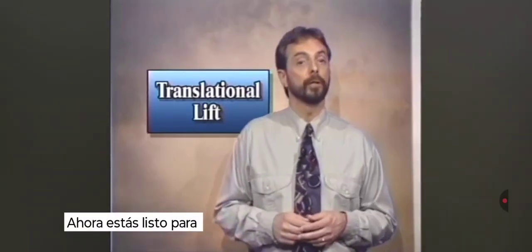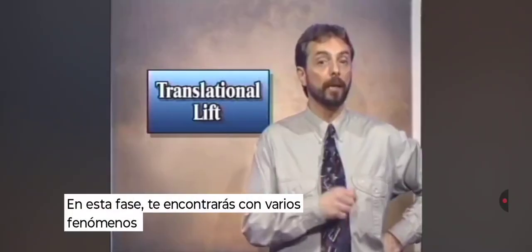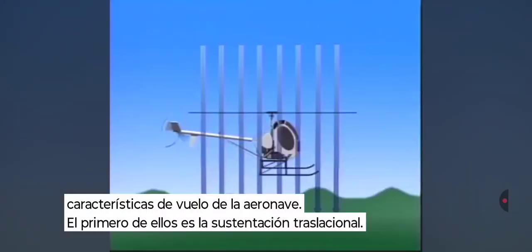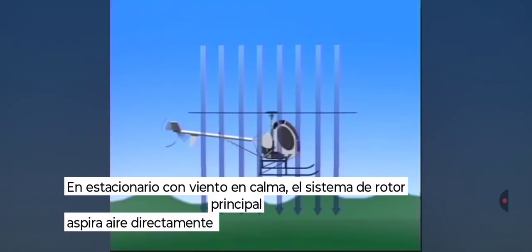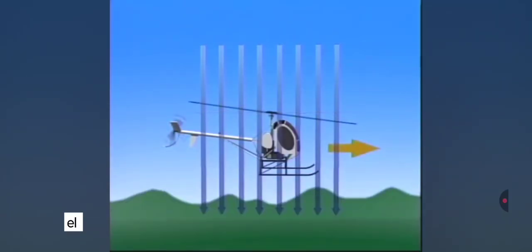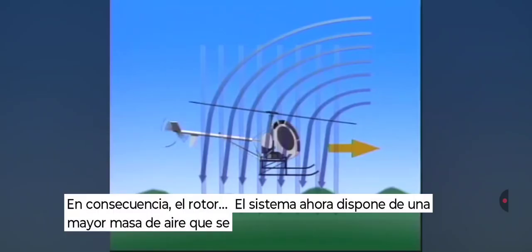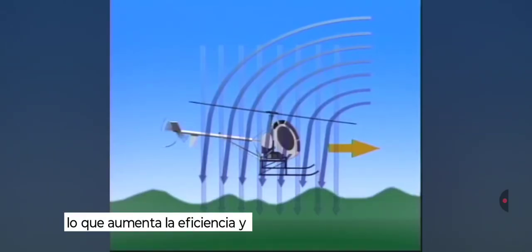Now you're ready to transition from a hover into forward flight. In this phase, you'll encounter several aerodynamic events that'll affect the aircraft's flight characteristics. The first of these is translational lift. In a calm wind hover, the main rotor system draws in air from directly above. But as the helicopter begins to move forward, the rotor system can now also draw in air from in front of the aircraft. Consequently, the rotor system now has a greater mass of air, moving at a greater velocity, to work with. This increases efficiency and performance.